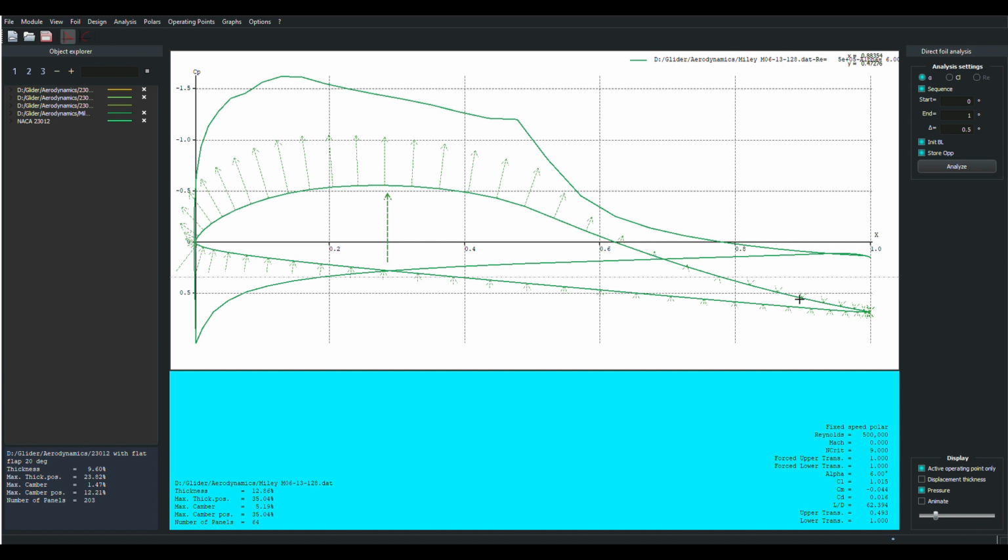And I know from tough testing that the elevons on the Swift, you can deflect them down 17 degrees before you start getting any significant separation of flow. So that's why the Swift was able to put on, and they have a V-notch in here. They use a V-notch off the upper surface, and they have nice flow conditions even though they cut the elevon out of the airfoil rather than sticking on a flat plate like so many others have.